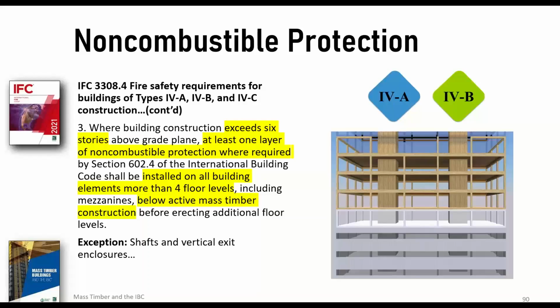construction. So note the word where required, because in type 4C construction, you're not required to cover the mass timber on the inside. Now, to say that all the mass timber is exposed on type 4C construction isn't entirely true, because in bathrooms and in kitchens, you're going to have to cover the mass timber not for fire safety reasons, but for hygienic reasons.